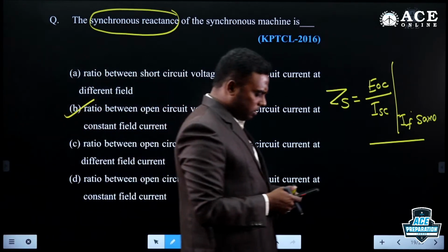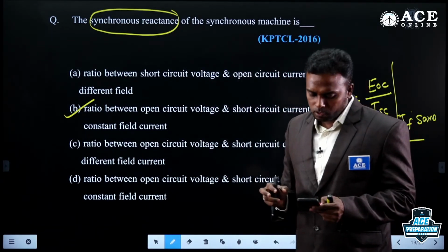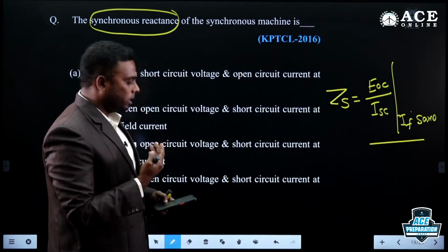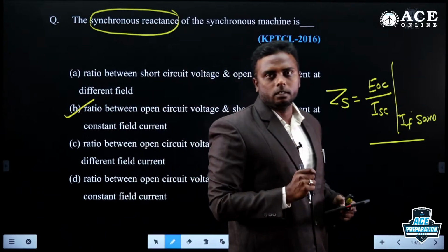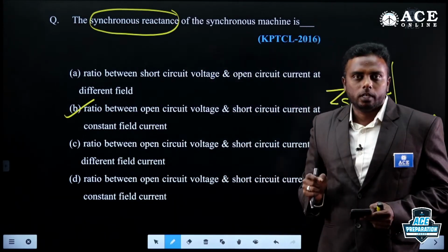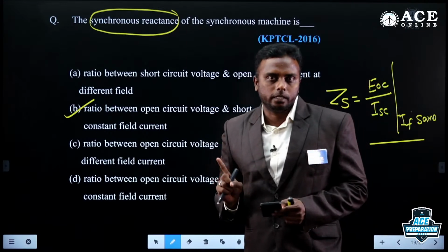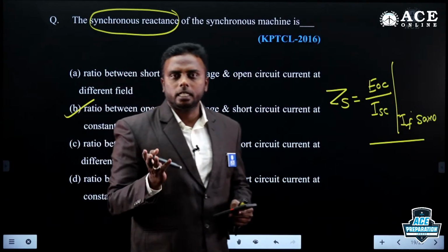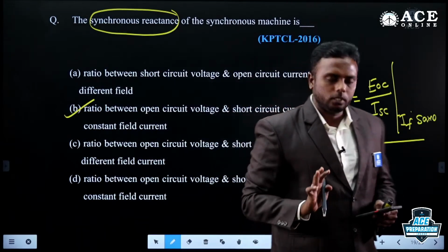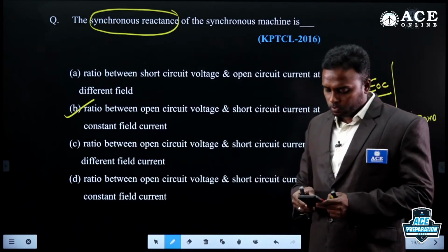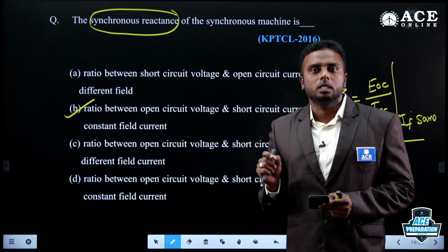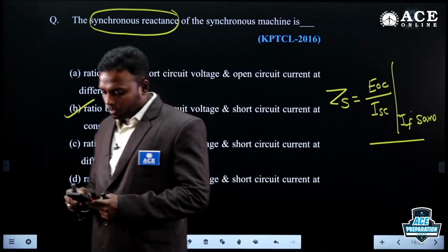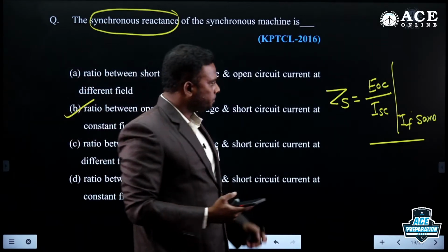Yes, depends on experiment values of that voltage and current we will get XD, XQ. But directly you can also find the magnitude relation. What is the test we conduct? Slip test to find XD, XQ. That is from measurement, and there also you get the same relation. XD is always the higher value, XQ is low. So we can say high or low, but how much the magnitude is, we cannot find out. That we can find only from experiment. Okay, next question.